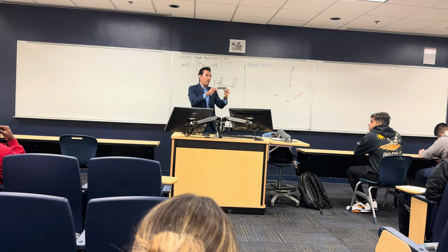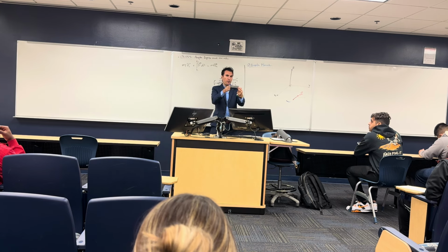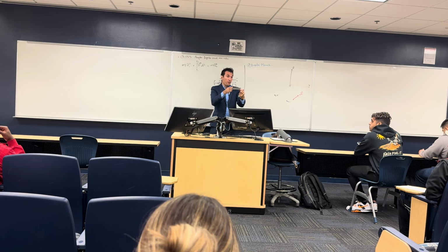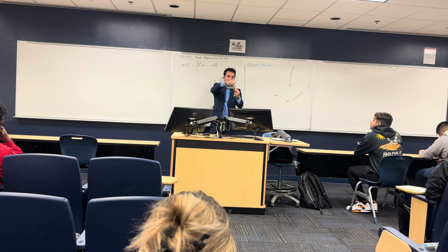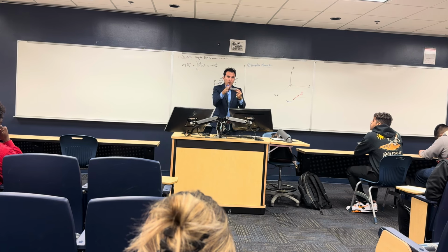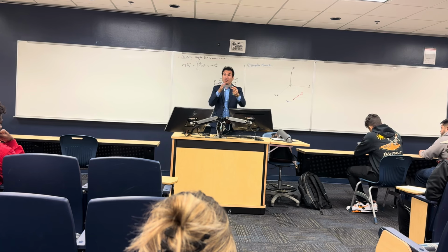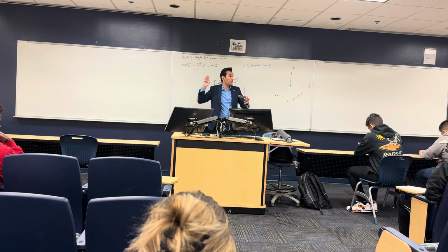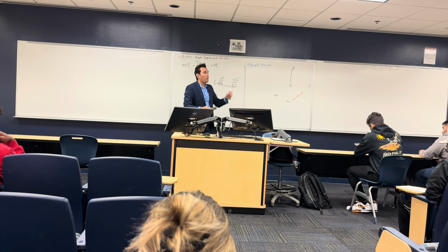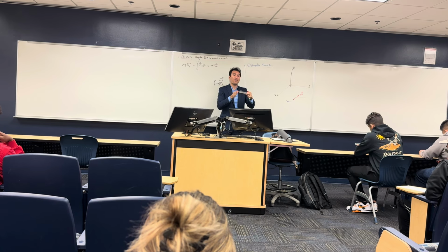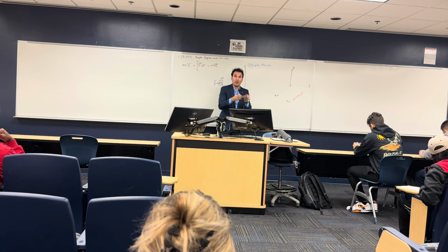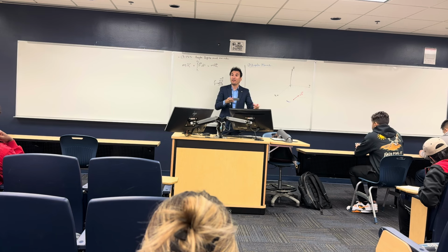Like for example, if I'm holding this from here and putting my force this way, so this is a force. It's a quantity different from the moment. If I want to find the moment about this point, I need to multiply this force by the arm of this force. So if this force is 10 and the arm is 5, you multiply 10 by 5, you get the moment, 50 ton meter or 50 kilonewton meter. That's the moment. The moment of any quantity is that quantity multiplied by an arm. So if you have a force, you multiply the force by its arm. If you have a momentum, you multiply the momentum by its arm.